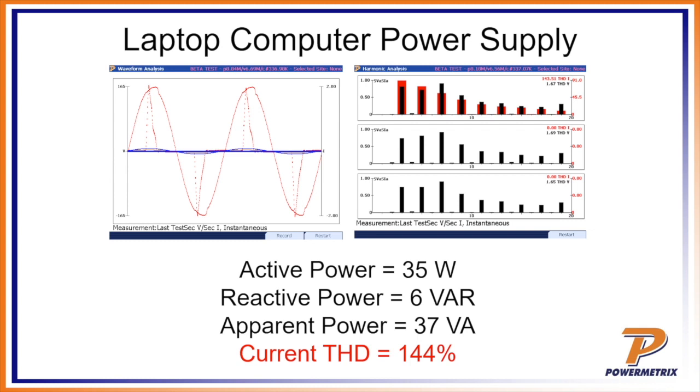Once again, if we look at the waveform, what you see is a sinusoidal voltage, but a really sharp peak on the peak and the trough of each and every cycle of the sine wave. I will say this: the sharper the peak, the more harmonics are going to be generated. Some of these switching power supplies out there are just not clean at all. They're really bad in terms of making a really sharp peak and a really high amount of harmonics, and as such that can really cause some problems for the grid.